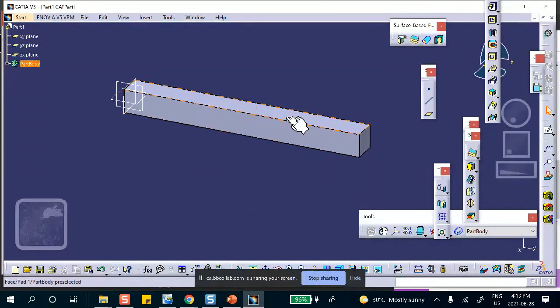You can use symmetry. For example, you can take only a quarter of that, because you can cut it along the length, and in the direction X, that'll be 1/4. However, if you do that, you will lose certain frequencies that may be critical, and you don't want to do that. Unless you know exactly what you're doing, don't use symmetry in buckling or natural frequency calculation.